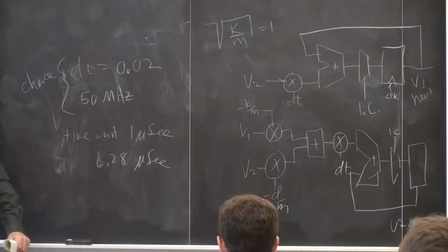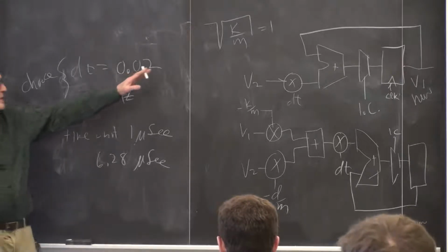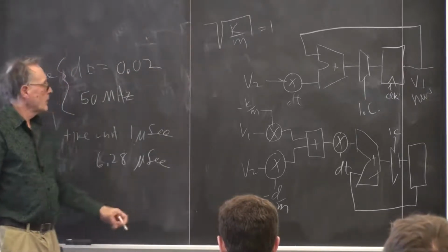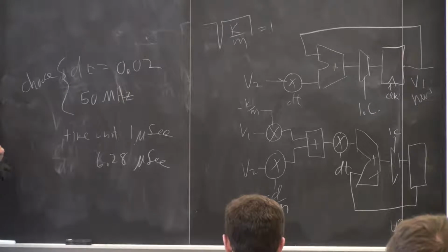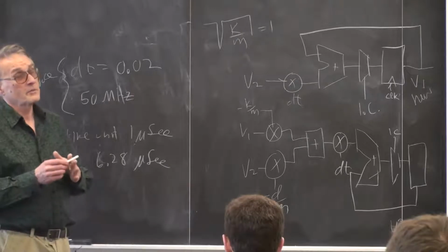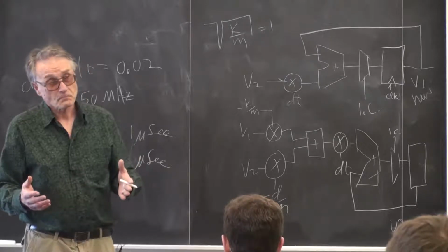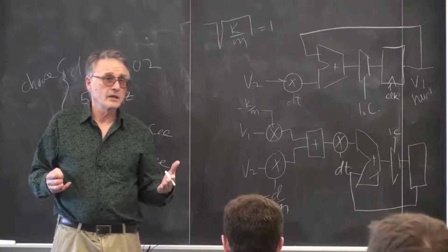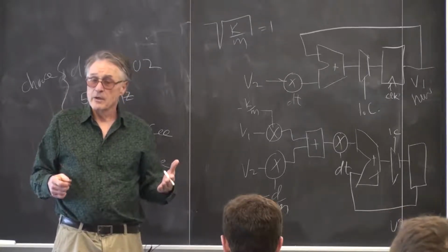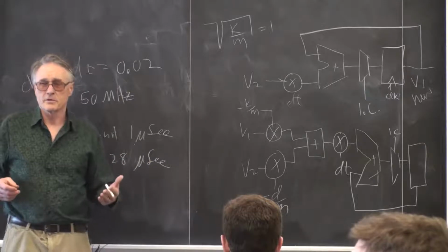So there are 3 ways of scaling the frequency. One is change k over m. Another is change the update rate. A third is change dt, but there's going to be a fairly narrow range for dt in this particular simulation because of the low accuracy of the Euler integrator. Too big a dt, and you're going to deviate from a sine wave. In fact, what will happen first is that the natural frequency will start to drift.